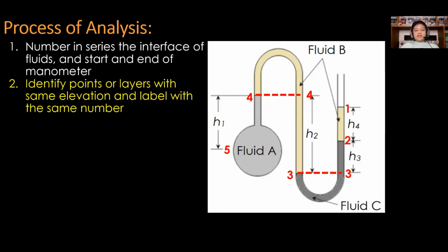So what does this mean? Within the scope of manometer, with same fluid, the changes in pressure are equal. So we have an upward and we have a downward pressure. Therefore, if we have the upward and downward with same intensity, we may already disregard these portions.